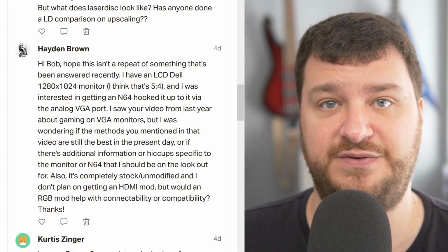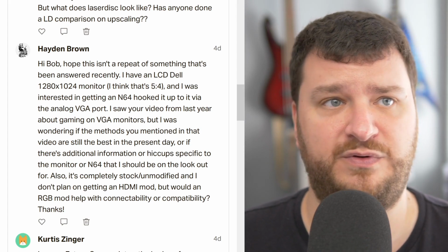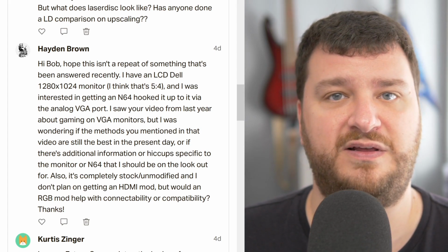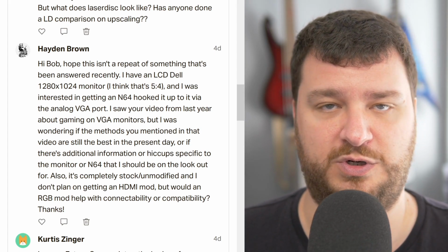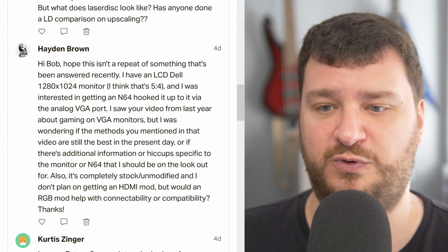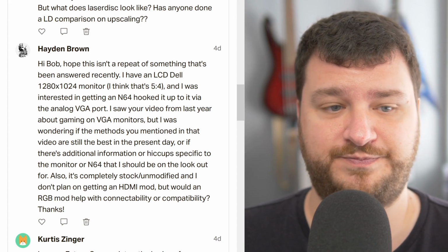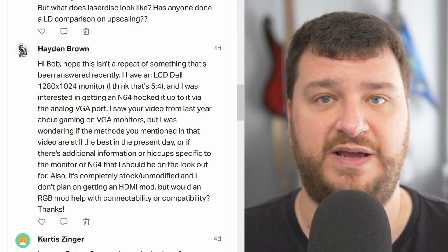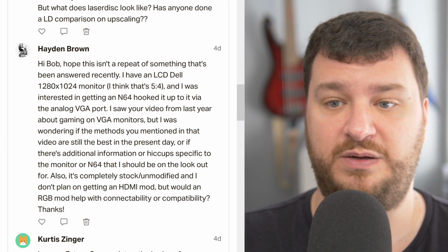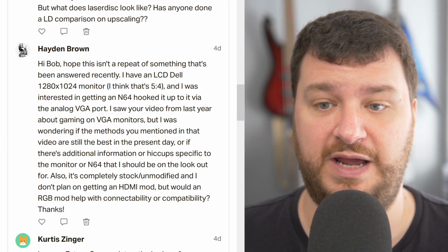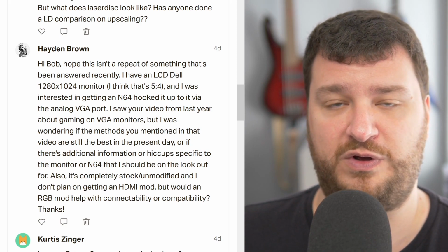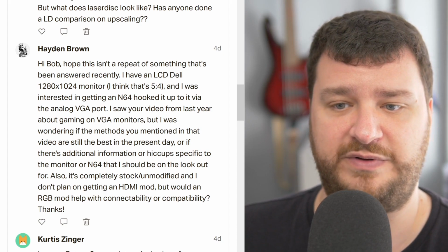Composite's fine on the N64, S-Video's sharper, and if you have an NTSC N64, you just plug it in. There's no worries about it. So anything that's not from Europe or PAL region would work fine. PAL, most can. You would probably just need to get the right cable for it. But basically just plug it in, run it through a basic HDMI to VGA converter, or if you have a DVI input, just get an HDMI to DVI cable, and you're still letting the LCD panel scale it from 720 by 480 to 1280 by 1024.